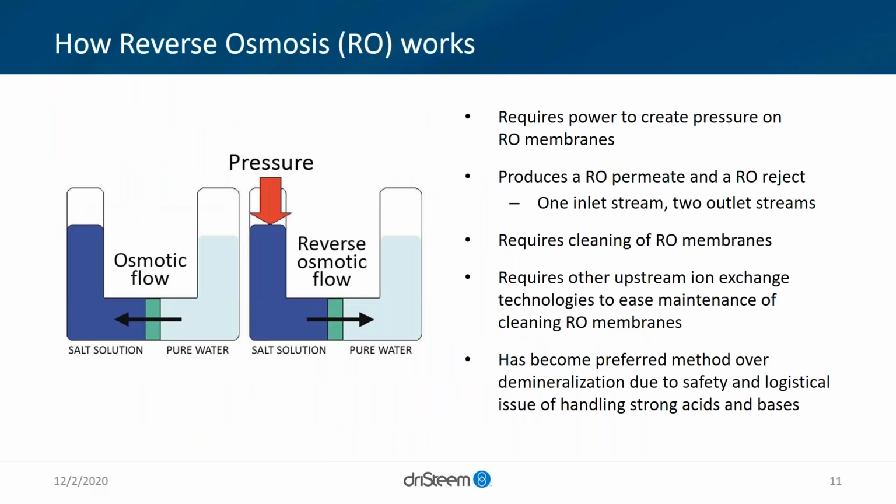So a little bit more about what the heart of the system does as we talk about reverse osmosis. Essentially, there is a barrier, which is the green part in this diagram, which is your membrane sheet. And on one side, you have clean water, and on the other side, you have the dirty water essentially coming in. And we're providing a pressure against that. And that pressure is what's really driving through the membrane the clean water, and leaving the TDS on the other side.